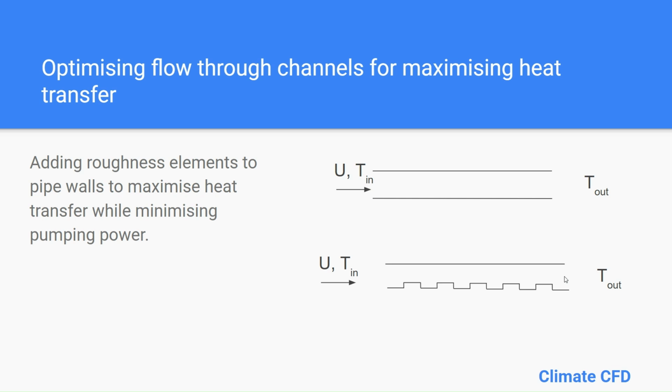So a really cool project, relatively simple if you set yourself up in Design Modeler at the beginning, specify the shapes in CAD with all the appropriate dimensions, and then just shoot through them. Make sure your heat transfer values are in CFD post as expressions, and then the data will just spit out into parameter set. Again, if you want to know more about that, you can always have a look at the previous video, which will be in the description.